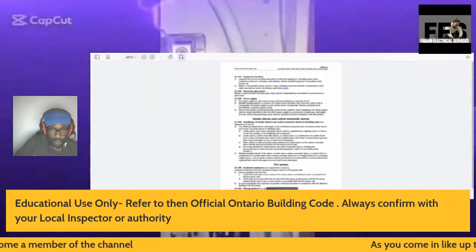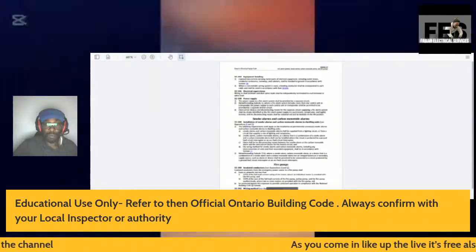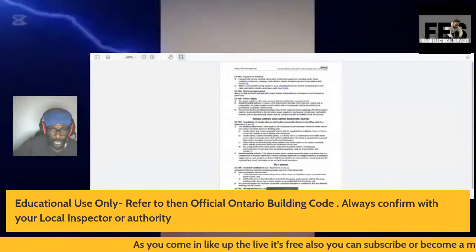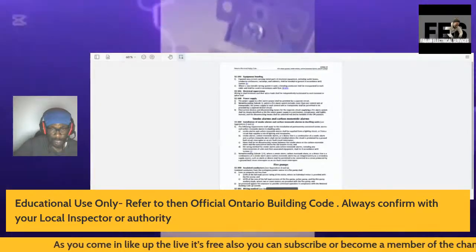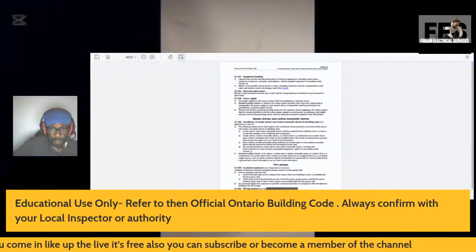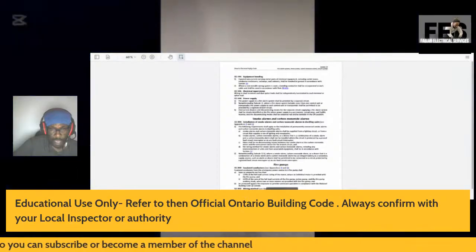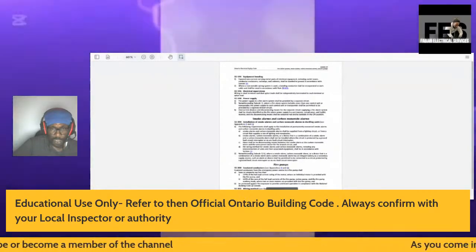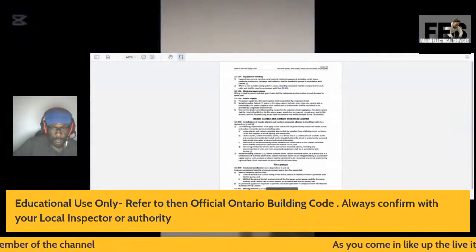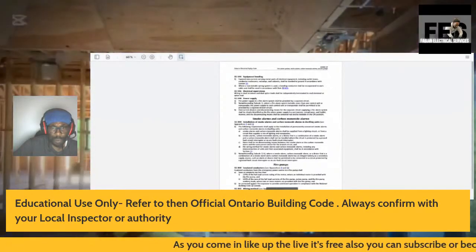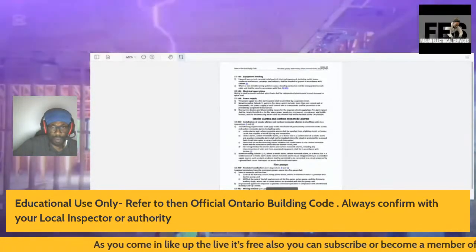You're going to see that I do supply the smoke alarms with a lighting circuit. That's how we do it in Canada. We provide the power through the use of the lighting circuit, and it has to be straight power, no switch to turn off the smoke alarm. You cannot have a disconnect in between.